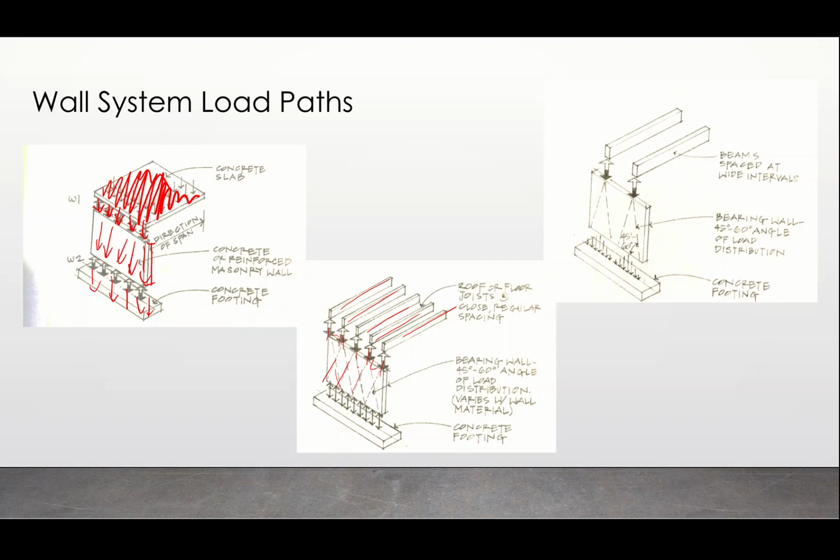They're going to go down in different ways. This one would be more straight down, but this one's going from side to side. But the way that those angles work out, everything's coming down nice and uniform by the time it hits the footing, which is not the case if there are wide spaces in between the beams here. So when that's the case, and there's just a couple, usually those forces, they're designing them to come off 45 to 60 degrees.